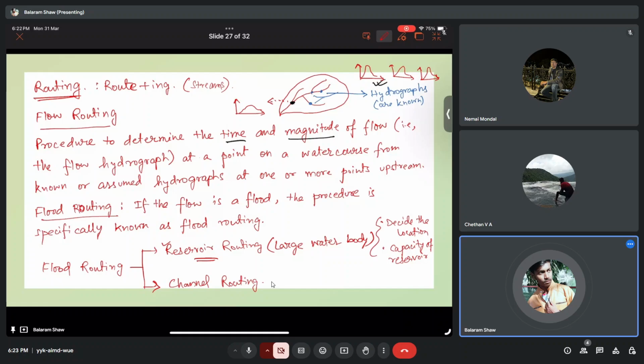We have studied this relationship before: for any reservoir, we will have one storage discharge relationship, which helps us understand the storage volume of the reservoir for some value of outflow. This relationship is very important to predict how the storage change due to inflow and outflow influences the discharge in the downstream section, so that we can take decisions based on that.